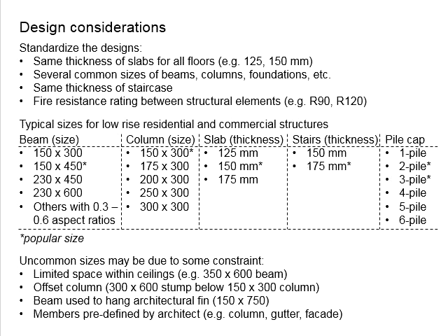It needs to be consistent, and probably you might need to check the requirements from the Bomba, which is the firefighting department, from the local authority, to see if there are any stated requirements in terms of the fire resistance rating. I believe it should be somewhere between 90 minutes and 120 minutes, and make it consistent throughout. This fire resistance rating will ultimately influence the concrete cover that you use in the structural elements.